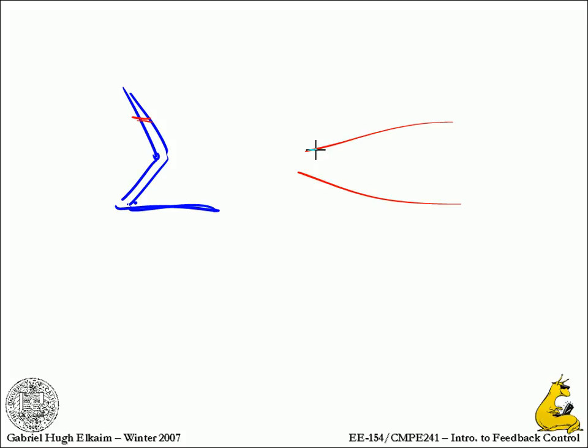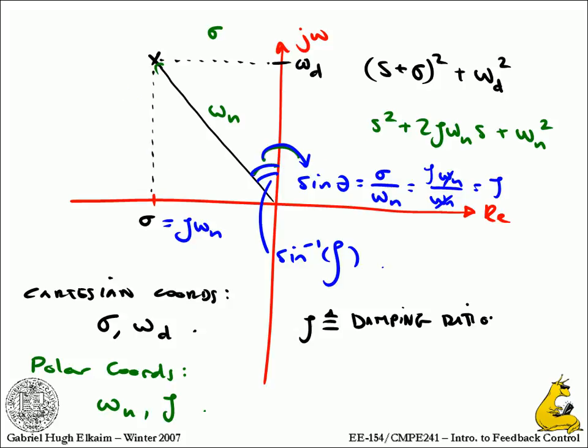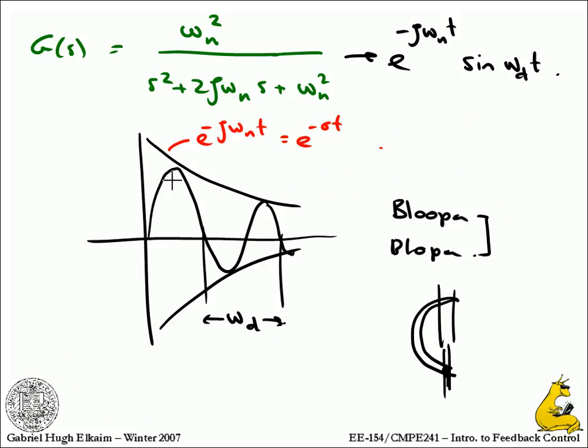Anyway, the whole point of all of that was that omega n is the resonant frequency of the system. So if you put an impulse in at omega n, even though the sine wave in the response is damped and therefore at a different frequency within the decaying envelope, if I drive it with a forced response at the frequency omega n, I get it to blow up, to inject energy in. That's the key.